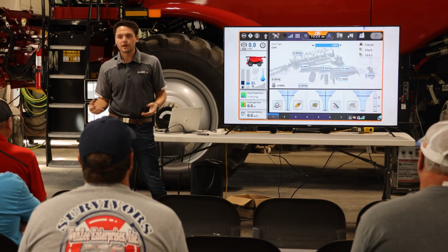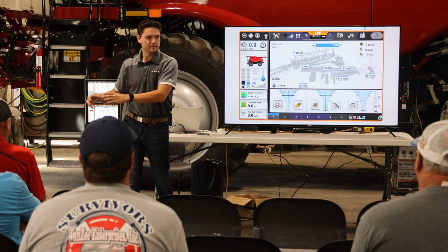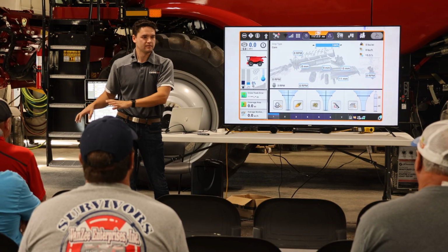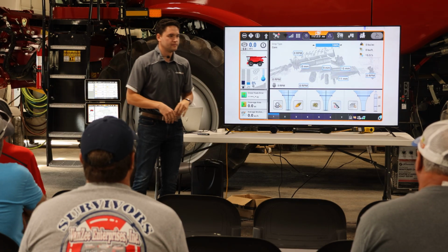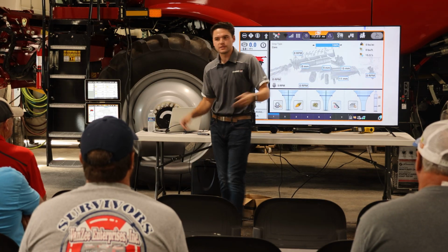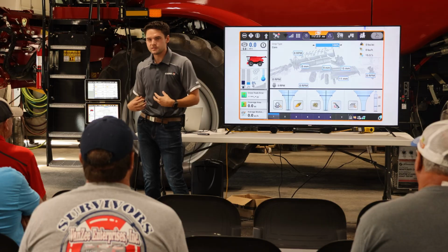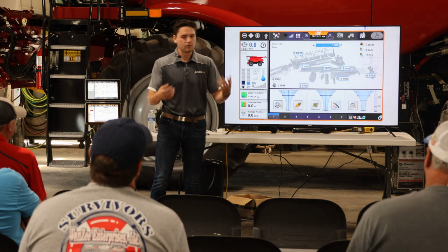But when we're running automation, we need to get in the habit of leaving this armrest right here alone. It just looks good in that scenario. That's all it's there for. It looks cool. We can rest our arm on it. But we have to let automation make the change, because otherwise we're going to be sitting there fighting. If we're the ones that make the change, automation will just set it back to what it thinks it should be at and run from there.